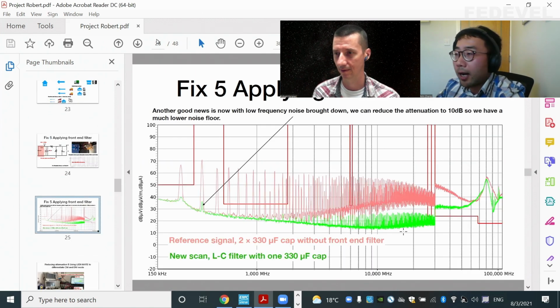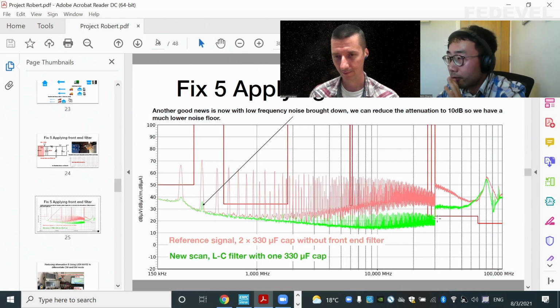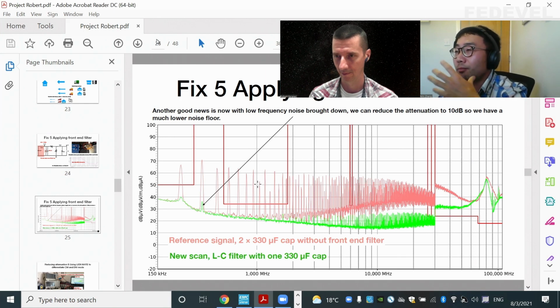And you can see now, finally, we have the result which is below the limit line. They are all now below the limit line. However, from 30 megahertz onwards, it's still failing. So we actually achieved good results. As I pointed out here, in this test setup I'm using a 33 dB attenuator altogether. So now I know that the noise level is lower than the limit, I can get rid of those attenuators because then we can see the results better.